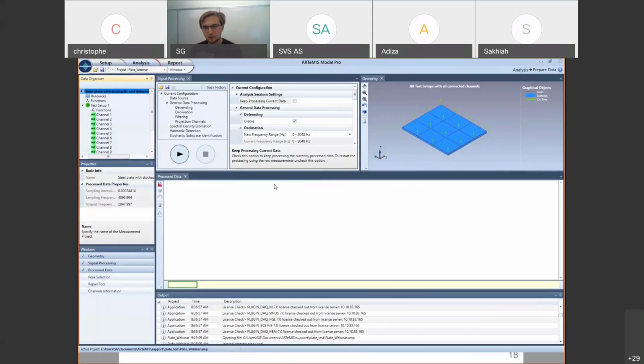It is a software for modal analysis, both experimental but also operational modal analysis, and also for structural monitoring. So there are many modal analysis techniques inside, both for experimental and operational. And today we'll be focusing on the data-driven subspace-based identification methods, which we went through in the slides.